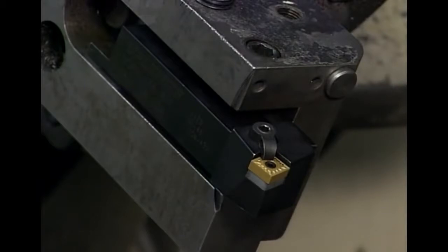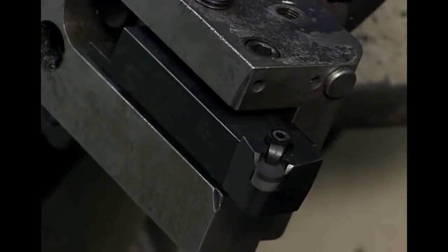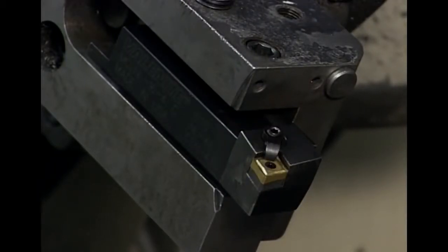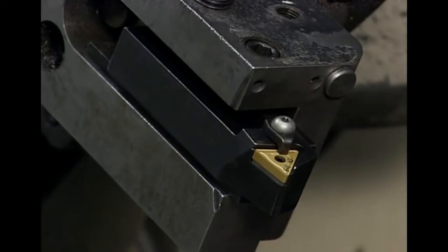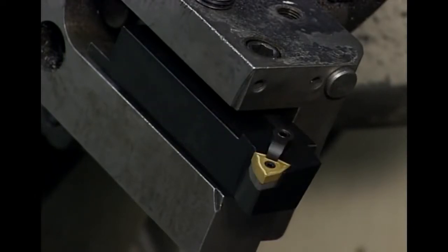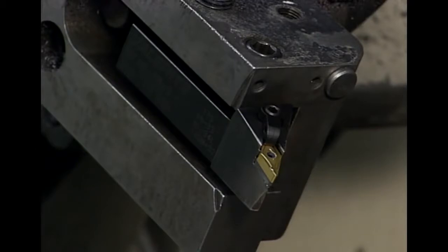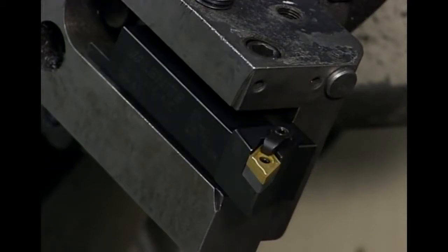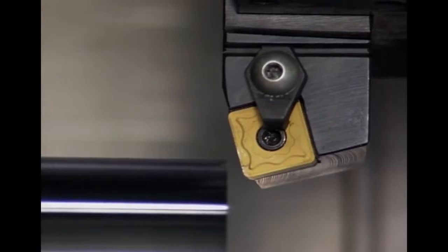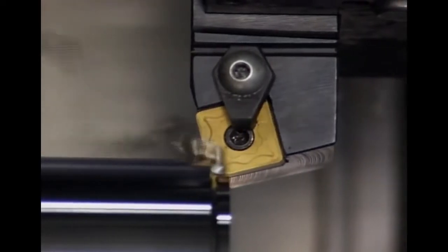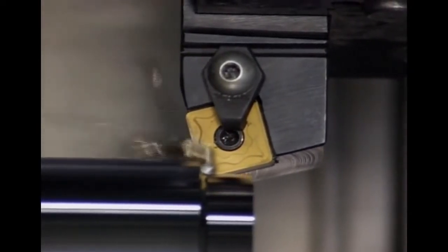Turning tool holder styles are defined by their lead angle and the shank offset. Longitudinal turning, facing, and various contour cutting operations require certain tool holder forms. There are hundreds of styles. In turning, a 15 to 30 degree reverse lead angle tool holder is often used.